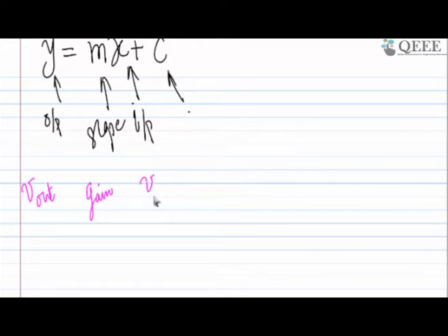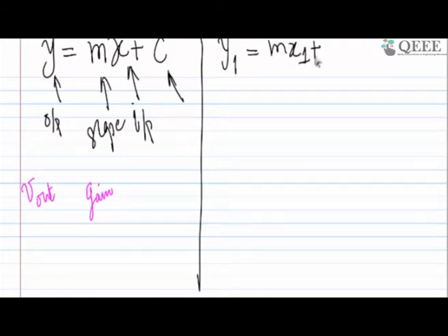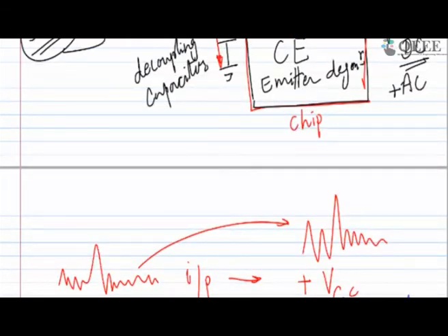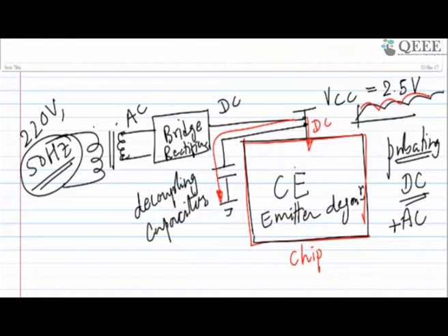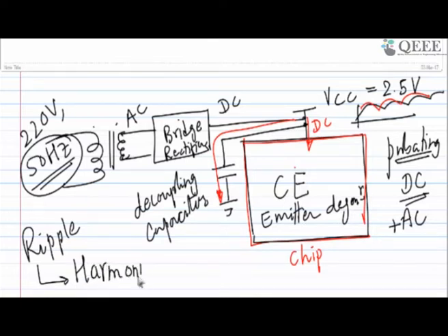So let's write the equation for our case. What I mean is that there are two inputs, one is x1. For x1, this may be the case that you have C, but this is the ideal case. There is nothing like ideal in the world, and you will have something called harmonics. If you remember the circuit when we started, this circuit has a ripple. Instead of ripple, I can call it harmonics also. Harmonics means it has some frequency components, it may be F, 2F, 4F, 3F. So those harmonics are there, and you can see those harmonics are affecting my VCC.